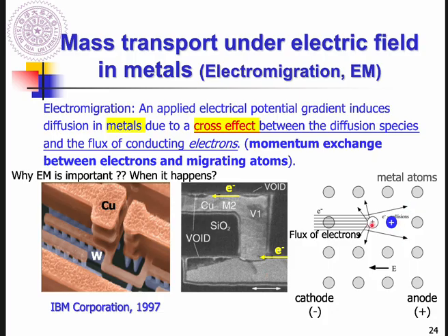As long as electron migration happens, each migrating atom leaves its vacancy, and as these vacancies get together they form voids. The voids get larger and larger, and once they cover a whole line, the circuit turns open and the device will fail.